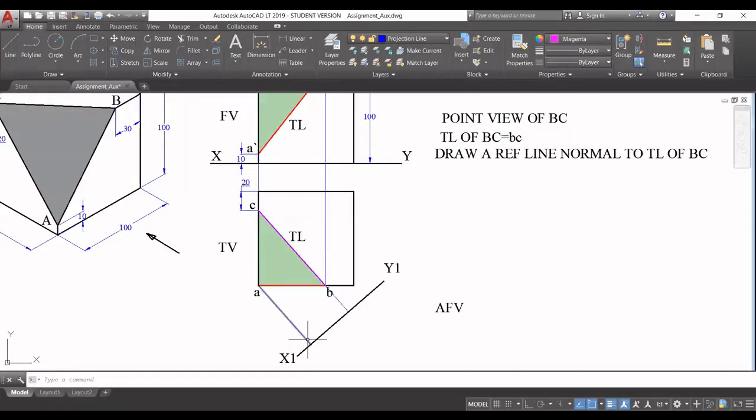So you just need to extend this line, click at this end. You can also use the lengthen command and just type in 10. So this 10 will make this projection line extend by this much amount. This increment is 10, right?